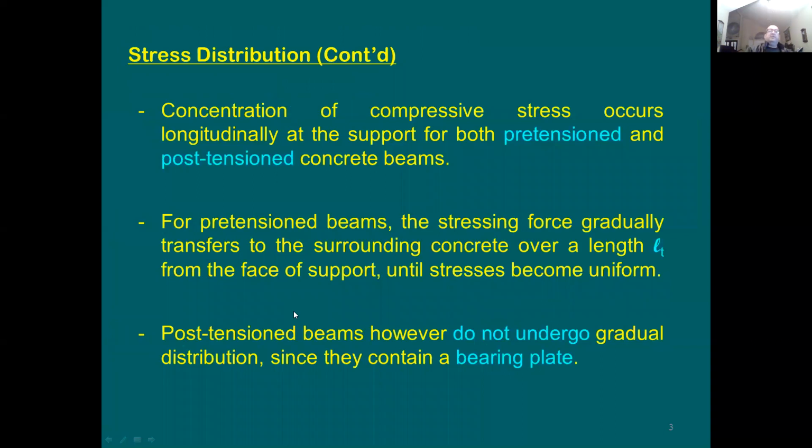Here is the stress distribution, with some comments on it, as I have it typed and presented to you. Concentration of the compressive stress is going to happen longitudinally at the end of the block. This is going to happen in both pre-tension and post-tension concrete beams.